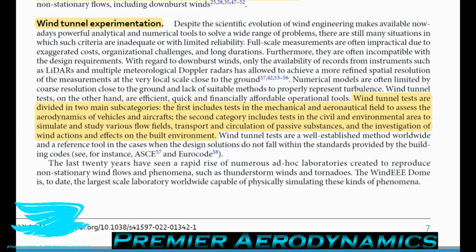Whereas with the wind engineering side of things, you can get a blockage ratio much higher, 10%, even 20%, and the results are still usable. The reason is, first of all, the flow physics doesn't change that much, because often the flow going around is for a bluff body. Secondly, in the environments where you find wind turbines and buildings, there are other things around constraining the flow. So there are often blockage-like features happening in real life, and you can get a higher blockage ratio in your wind tunnel if you like. So these are the different types of wind tunnels and the differences.